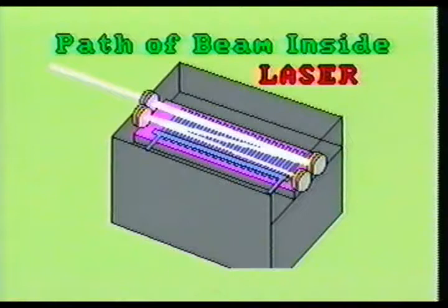The purpose of the folding mirrors is to force the photons to pass through the excited gas molecules, thereby increasing the strength of the laser beam. The folding mirrors, in effect, allow more power to be generated from a shorter cavity laser. If the beam is folded 3 times, the power output from the laser would be the same as a laser which had a cavity 3 times longer.